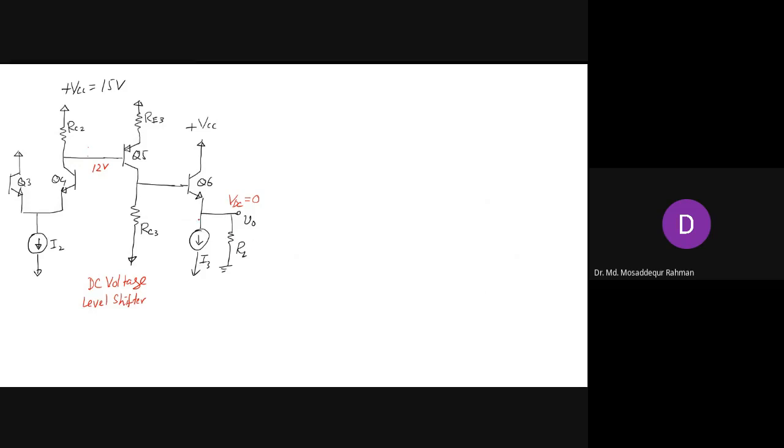So now if the voltage here is 0, you will have a 0.7 volt drop here, plus minus. It is the biasing voltage for the base-emitter junction. And if you have a 0.7 volt drop, then the voltage here will be 0.7. Right? The voltage here should be 0.7. So this circuit should be such that you have 0.7 volt DC here.